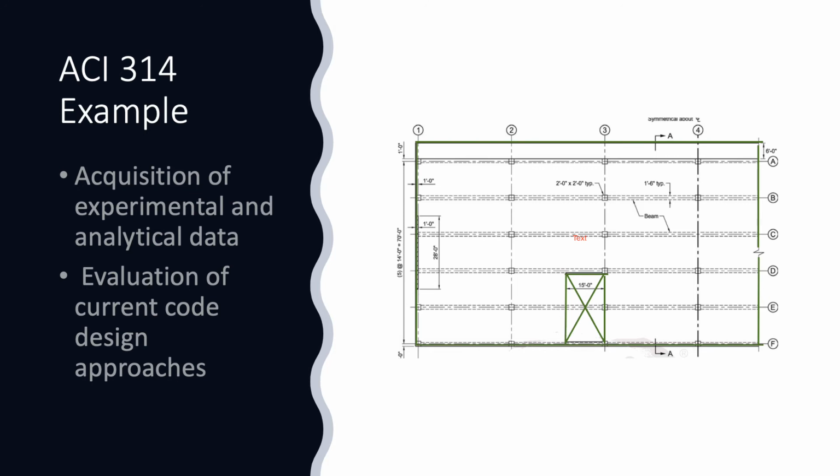Expanded shale, expanded clay, and expanded slate are the main materials for the production of structural lightweight concrete. The current design code approach does not distinguish between different types of structural lightweight aggregates. These aggregates are produced differently and are totally different from each other, but ACI follows the same guideline for all of them. By research and experiments, we will get a different lambda, which is basically the ratio of f't to f'c, and then compare it to the ACI lambda.